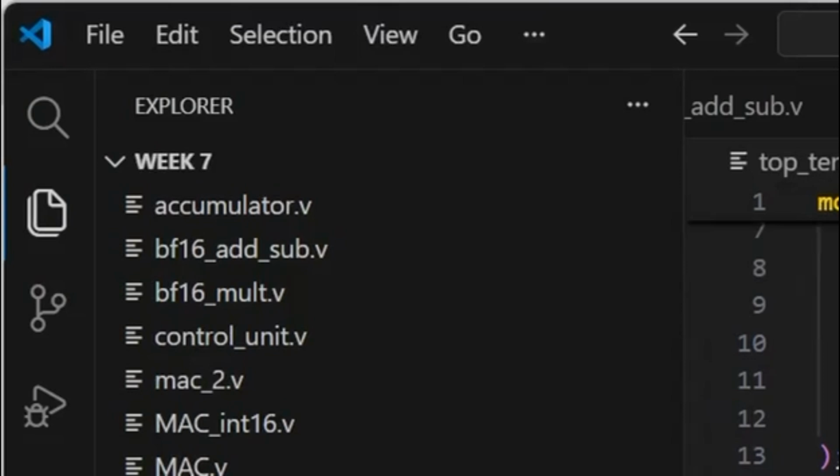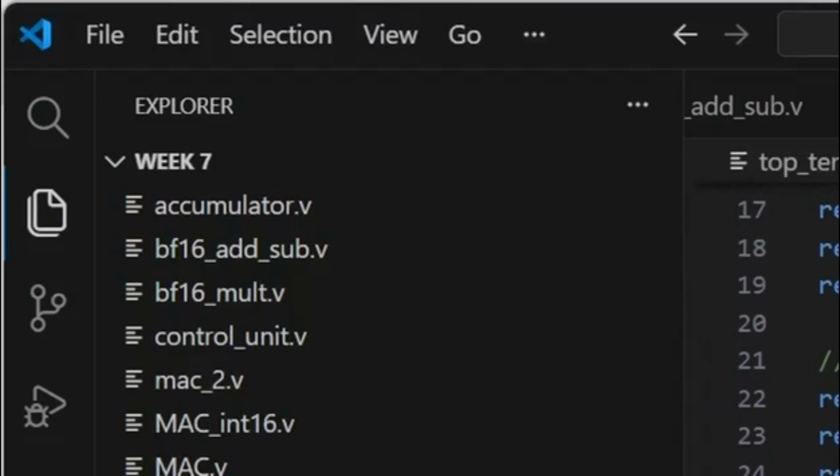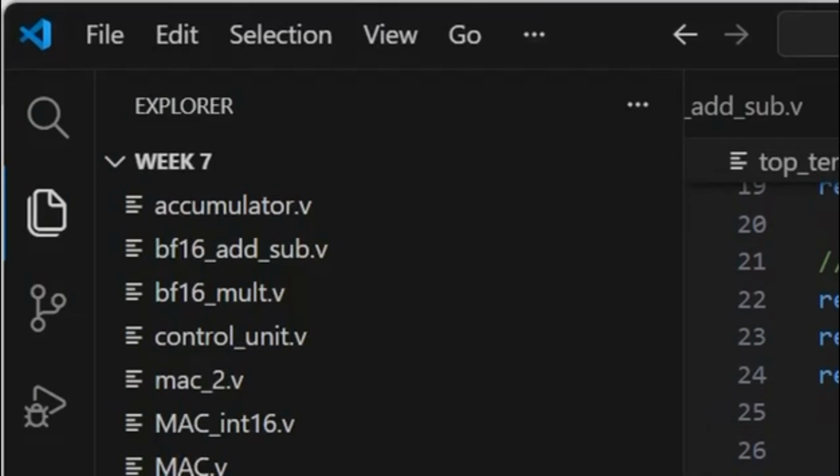And then yes, this is our ABC: C for accumulation, A and B will be multiplied, and D will be the output. So we are writing it into the array. This is the logic for the array. Okay, these are the write pointers for A and B and C. Basically, when it's write enable, the pointer will be constantly increasing, and based upon that, it will start from i, j.